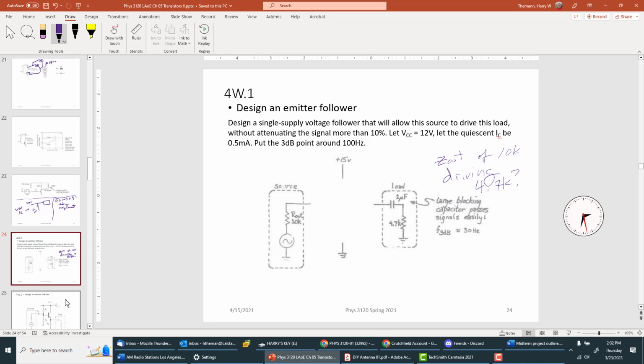They're not NPN transistors, but imagine I've got these three slabs of semiconductor, and if I want to make things smaller, you imagine that the base is smaller and smaller. At some point, the conduction electrons start tunneling across the base, and that becomes an output signal, even if the transistor is doing nothing.